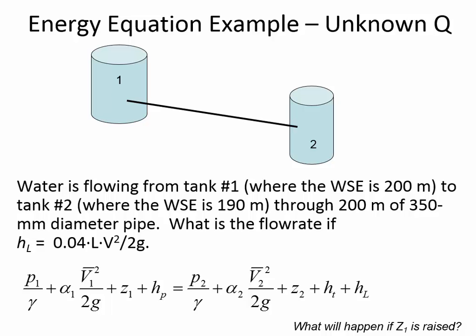Like if there is some pipe that continues in both directions, but we measure here at 1 some pressure, and here at 2 we measured, like, P is 100 kPa, and we measured at another point that the pressure is 90 kPa, even without having X-ray vision, I can't see into the pipe, but I still know that the water's going that way, just because water always flows from location of high energy towards low energy. That's why it goes downhill.